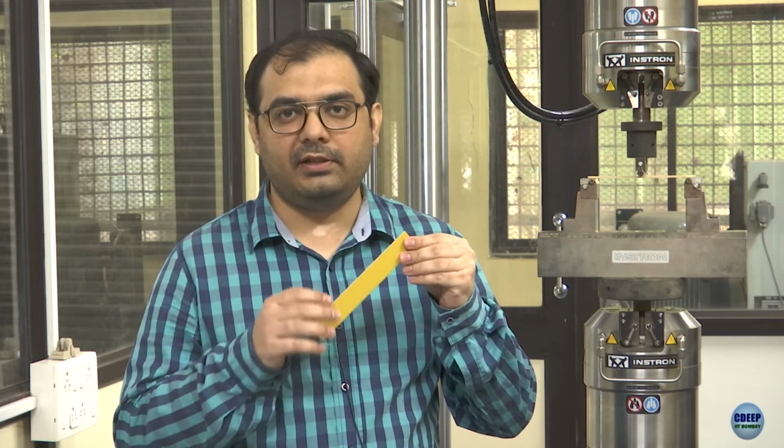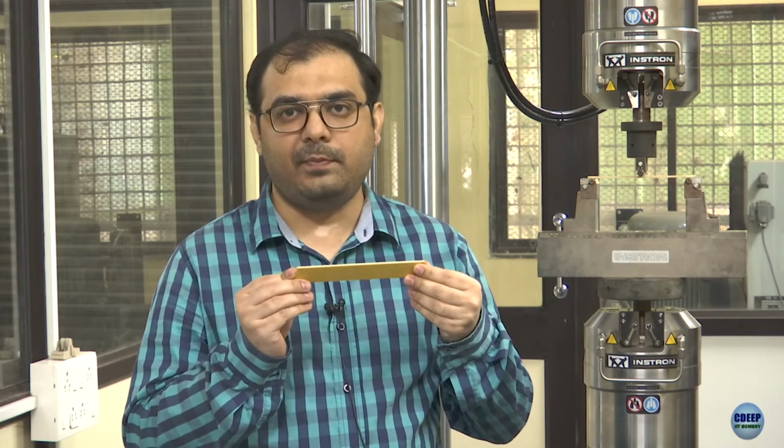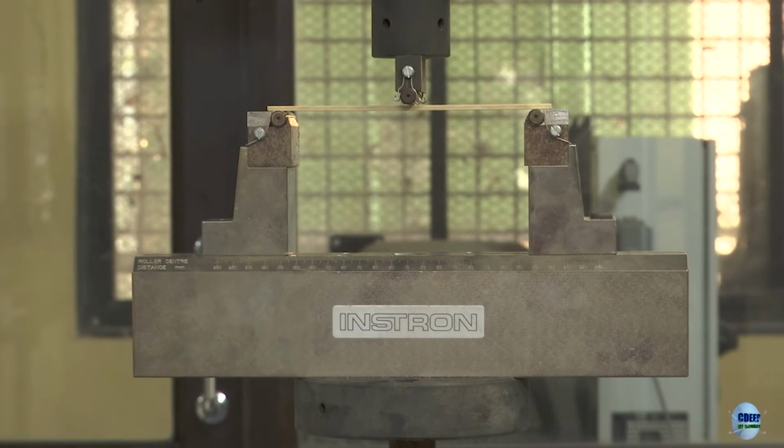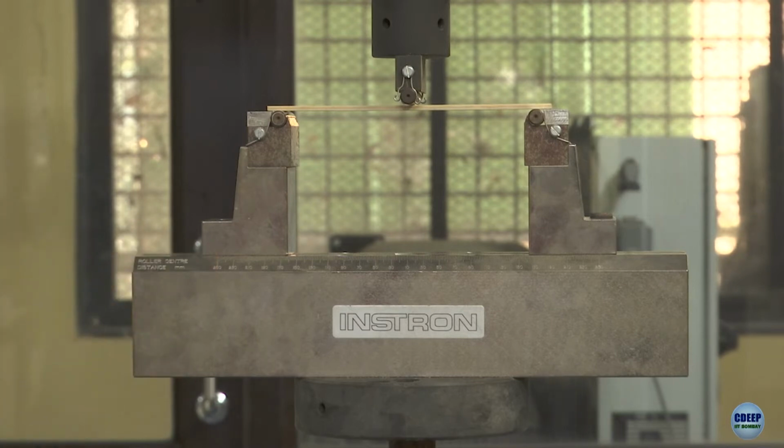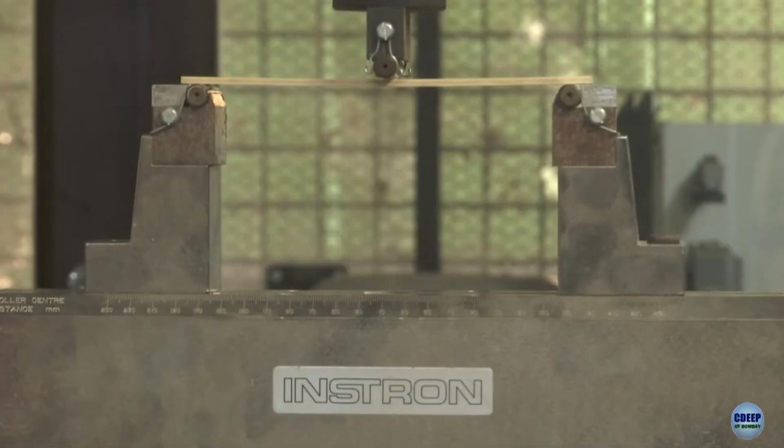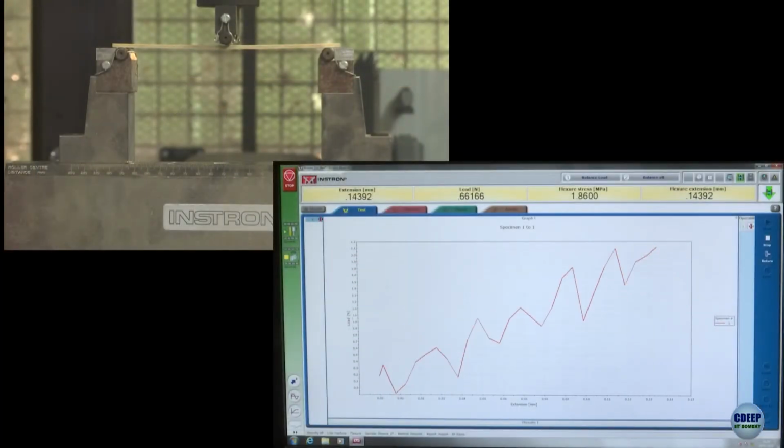The first step is to measure the dimensions of the specimen. We will be measuring the thickness, the width and the total length of the specimen. The next step is to align the specimen in such a way that it is exactly under the loading nose. We can see the markings on the lower base. It is set according to the support span. The support span for this material is around 162 mm, so we get an S/D ratio of 54. Now the test starts, and when the transverse load is applied, the top surface goes in compression and the bottom surface goes in tension.